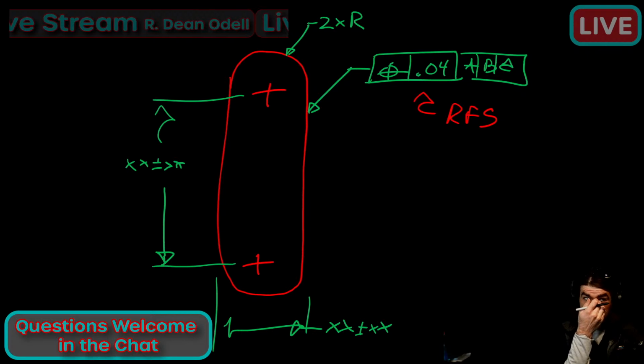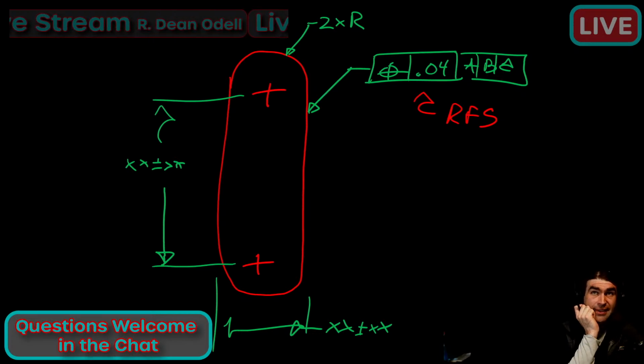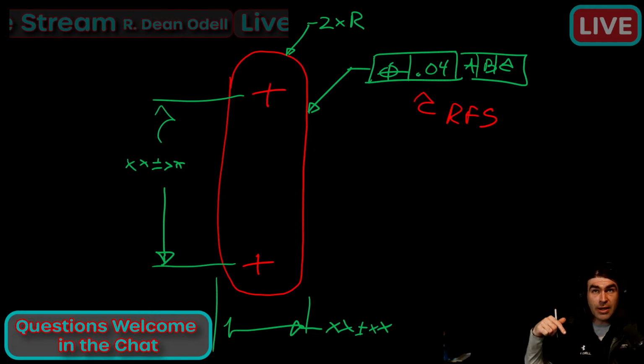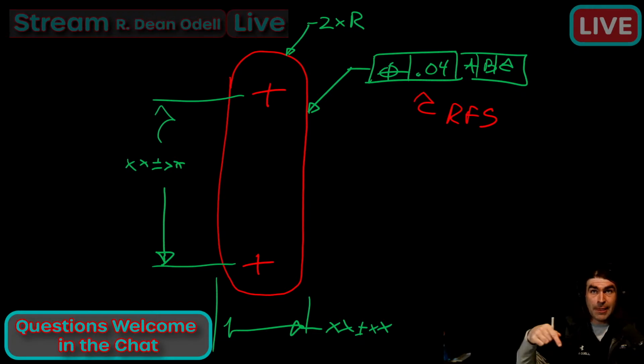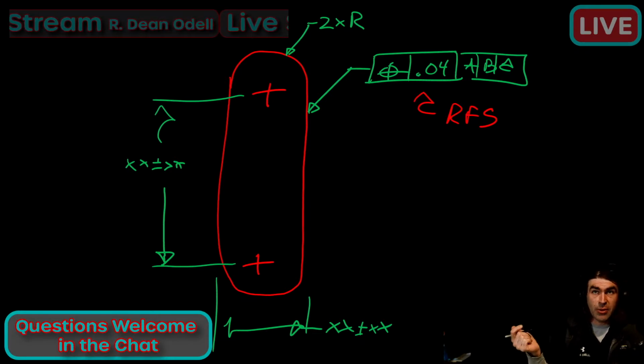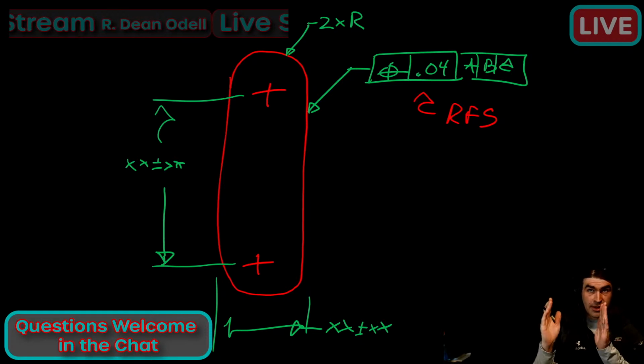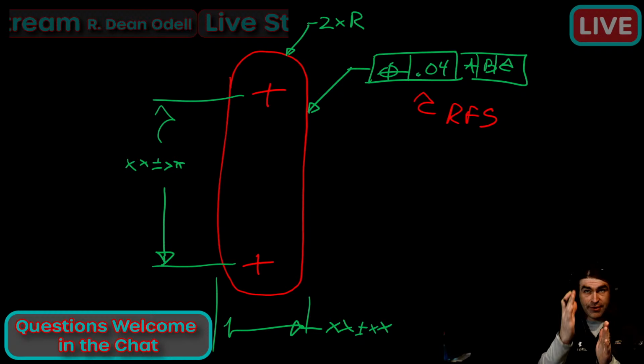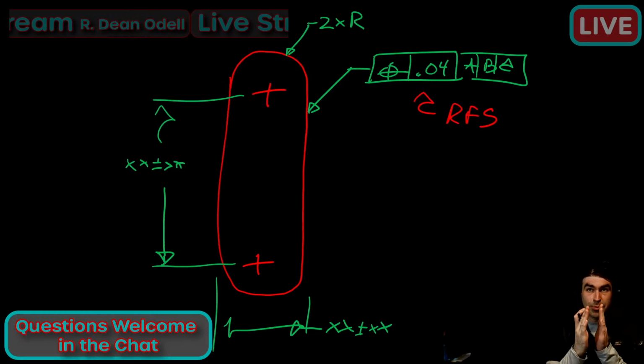I think I made a video about this one time, surface versus axis method. Don't worry about all that for now. Basically when you measure a hole, you get an axis, and you see if it's in a cylindrical tolerance zone. If you're measuring a groove, you find the center plane and see if it's within 2 planes.